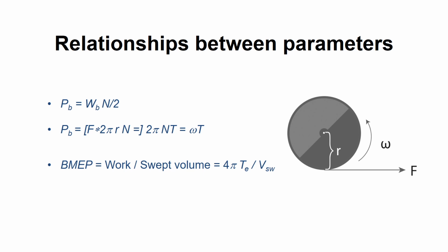For a naturally aspirated engine, that is, with no supercharging, full load is equal to approximately 10 bar. Bar is here used as the unit since it is convenient to use simple numbers. Also, an engine running at 2 to 3 bar is running at low load.